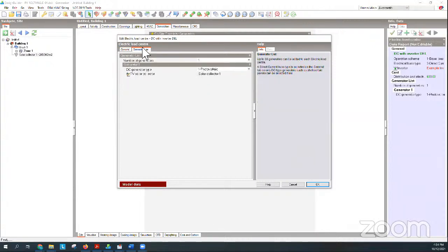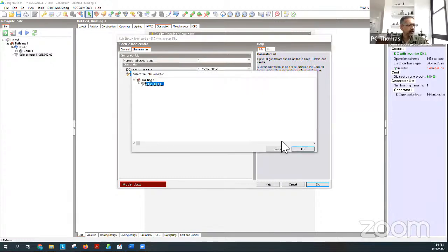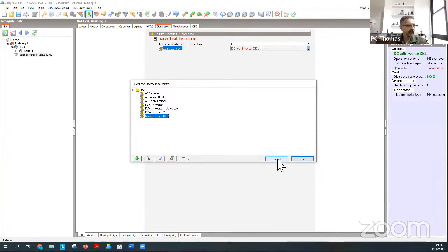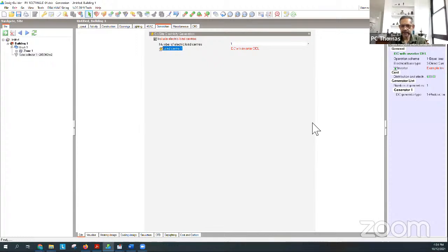You do get fairly sophisticated in what you can do with the different systems once you start playing around with it. Initially, my advice is just start getting it working. Once the numbers start to come out and they look reasonable, then you try and update the PV system type and the PV system efficiency and the inverter efficiency and all those things. Like in any other system, like when you're doing HVAC, same sort of deal.